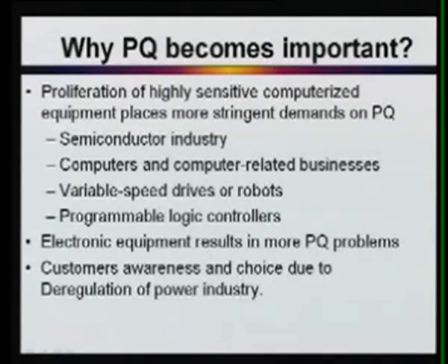If you have higher harmonics, one obvious effect is that the core loss will be more, because the frequency is higher than your normal supply frequency and is added on your fundamental component. This leads to more loss and more heating, and more heating may reduce the lifespan of your equipment.